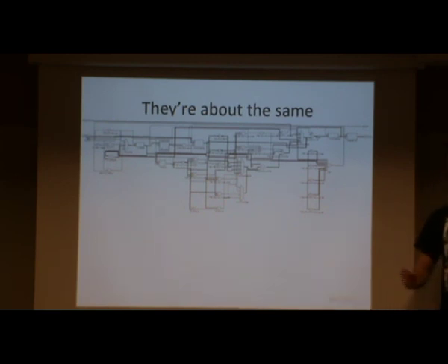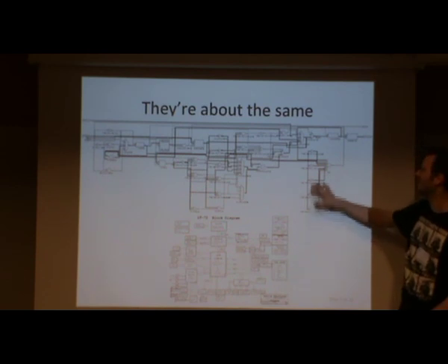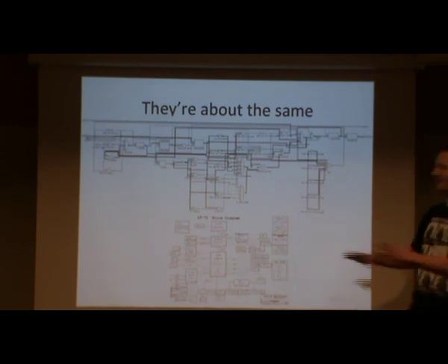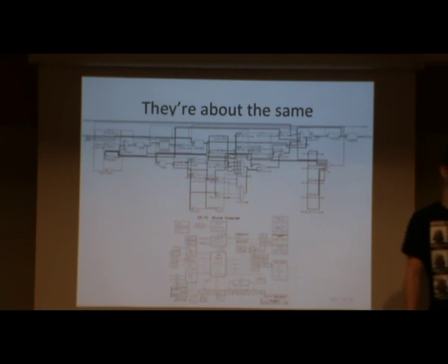Then once they're all finished, they look at this diagram. They get something like this, and then they have the original diagram they had in mind. Of course, I just picked these from Google. But the idea is that they compare the diagrams, and check that the synthesis tool didn't accidentally throw stuff away, which actually happens sometimes. It messes up some output and says, this output's no longer needed, so everything that was driving that output I can throw away. And suddenly your circuit becomes a whole lot smaller than you expected, because of the synthesis bug.